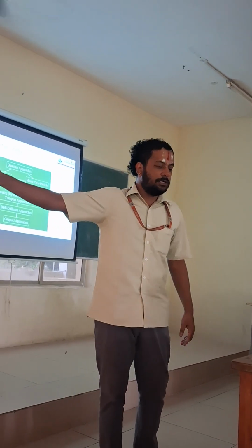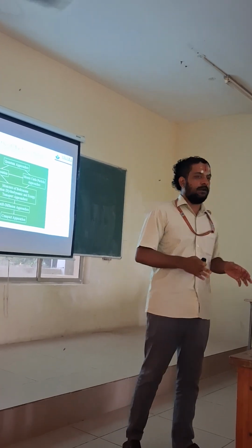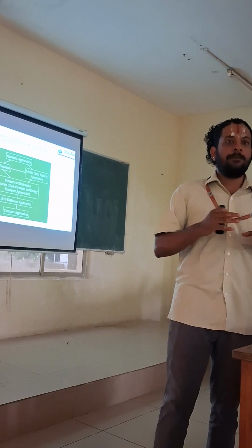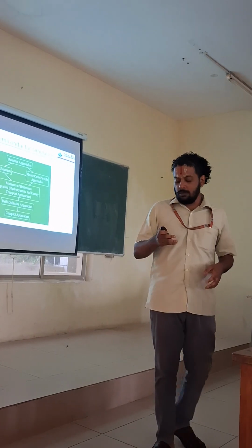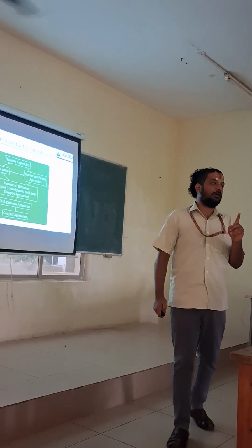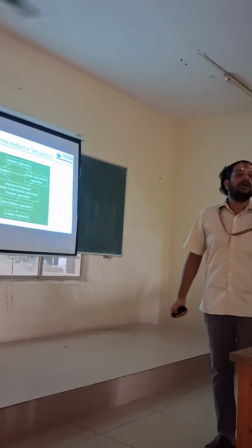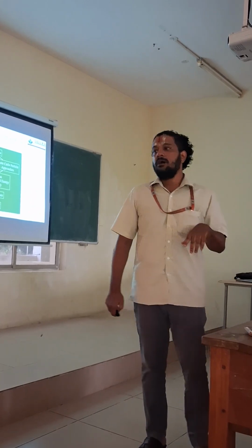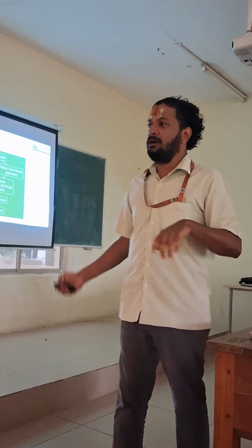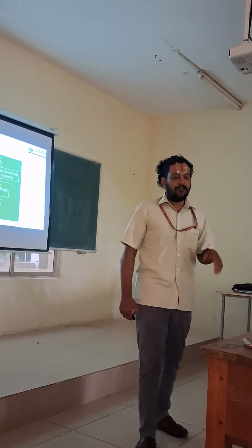We go all the way to t equals negative infinity, and then we try to iteratively solve to the current particular time, where each time step has a dependence on the events of the previous time step. So this is considered to be an extremely difficult problem to solve, and as you can see, the drift diffusion approach will probably be accurate when it comes to devices that are in the micrometer region. The hydrodynamic approach will be sub-micrometer region, and the Monte Carlo approaches will be more suitable for devices with channel